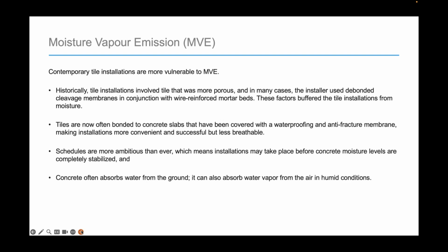Schedules are more ambitious than ever, which means installations may take place before concrete moisture levels are completely stabilized, and concrete often absorbs water from the ground. It can also absorb water vapor from the air in humid conditions.